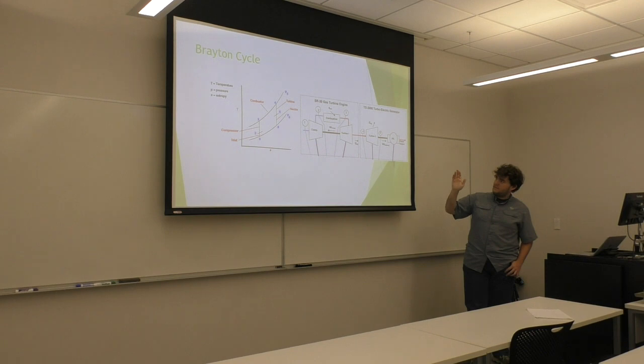It then goes to the combustor, where the fuel burns, increasing temperature, pressure, and enthalpy, and then feeds to the turbine, where it drives the compressor to keep working, decreasing temperature and pressure. For the engine, it would shoot out the back, propelling the aircraft. But here it would then push into the generator to turn the second turbine to produce the power needed.